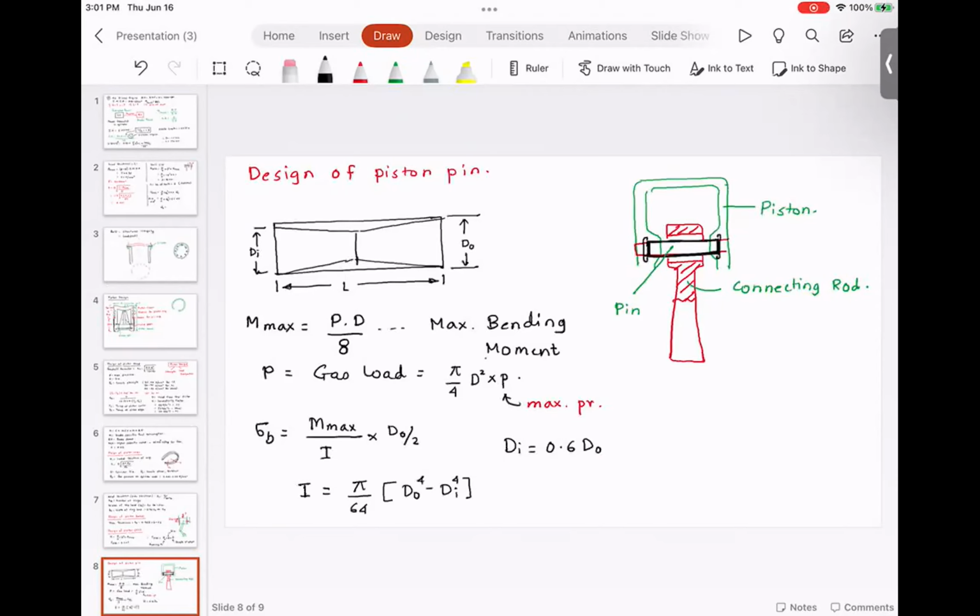So basically, if you look at the diesel pistons, they are stronger. And the heat dissipation equation for the diesel pistons is really different. But if you look at the textbook, they are just using one single equation for the piston design.